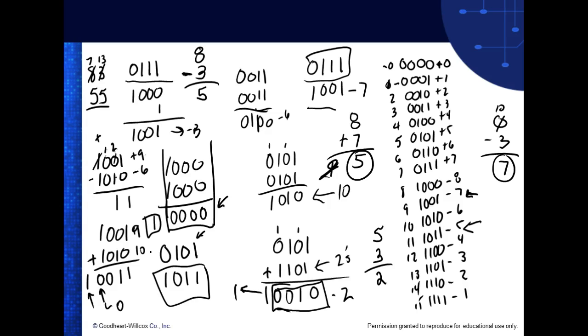So what do you do with the carry? Well, if I was dealing with signed numbers and it came up set, then if the number was positive, I would know it's really supposed to be what? Negative. Or if the answer was negative, I know it's really supposed to be what? Positive. If I get a carry bit, then I would just use the carry bit as part of my number.